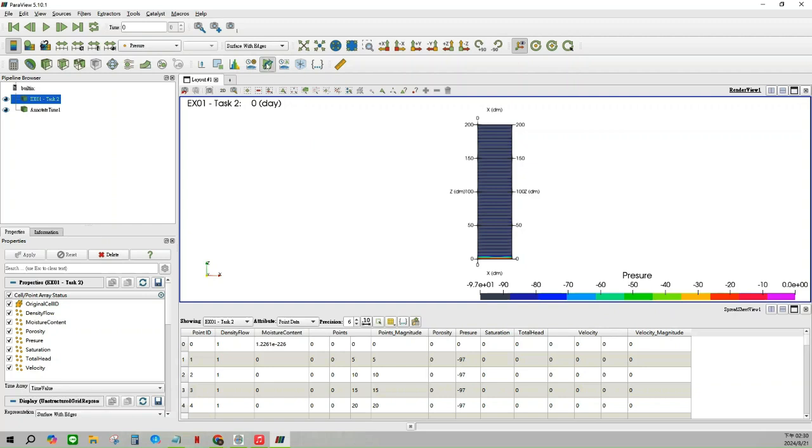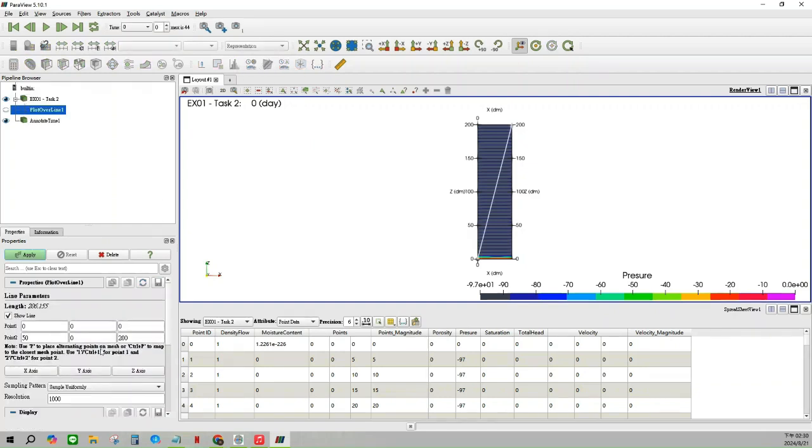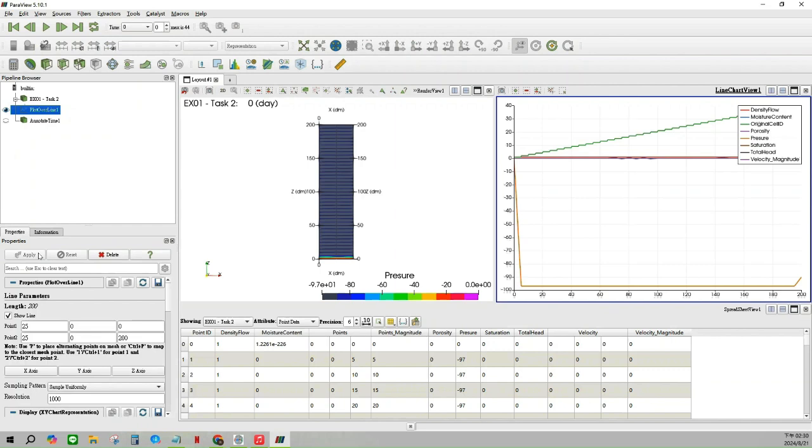Click Plot over Line, then the graph will show the line. Click Z-axis, the line segments in the graph will become vertical to the XY plane. Click the visible icon, indicated by eyeball, on the left side of the tree view nodes, then click Apply. A line chart will appear on the right side window of the screen.